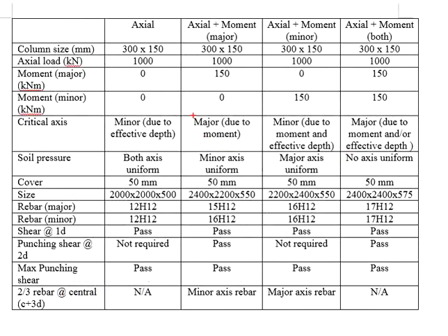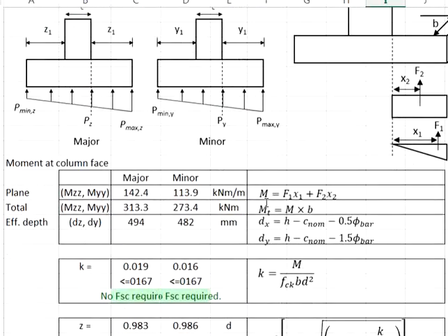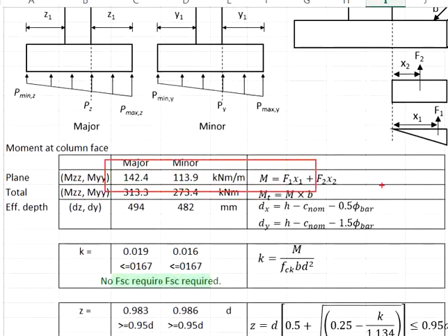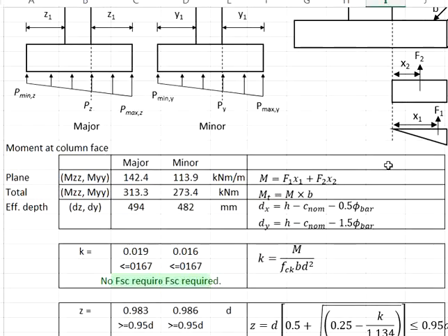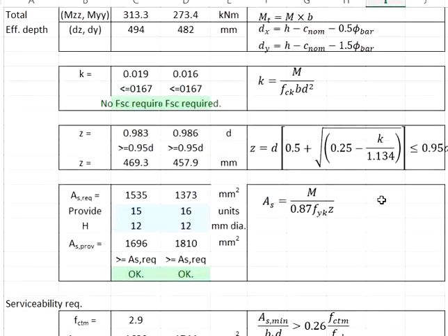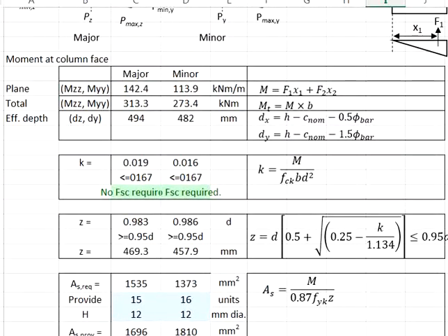Due to the changes in the soil pressure, your calculations of the moment would differ slightly. And then, when you are proposing a rectangular section, you will need to be extra careful, especially when it comes to the width B. This is the area that most students may have issues with.